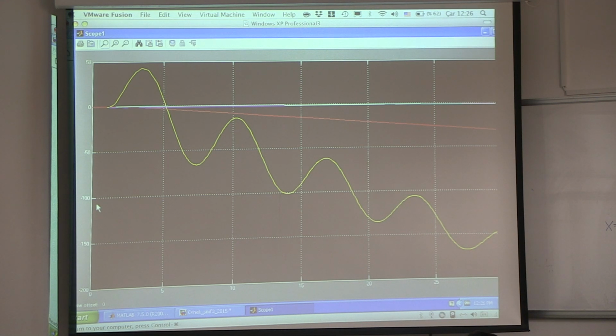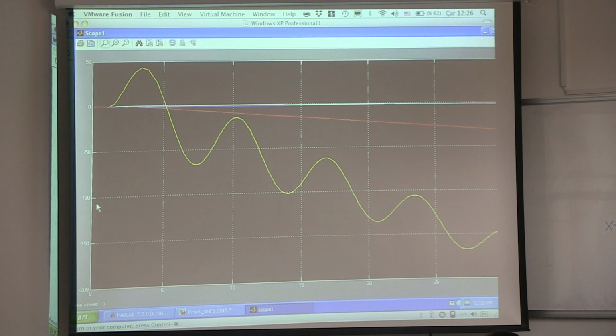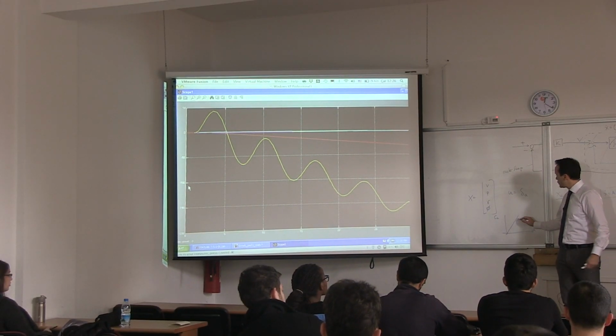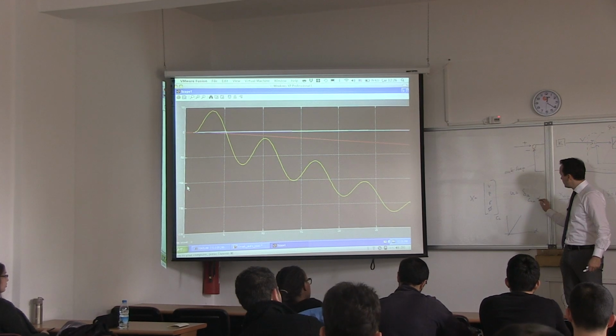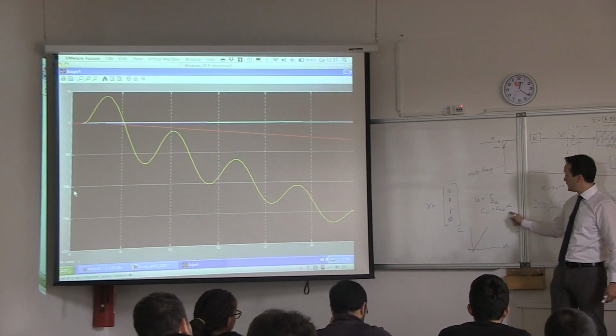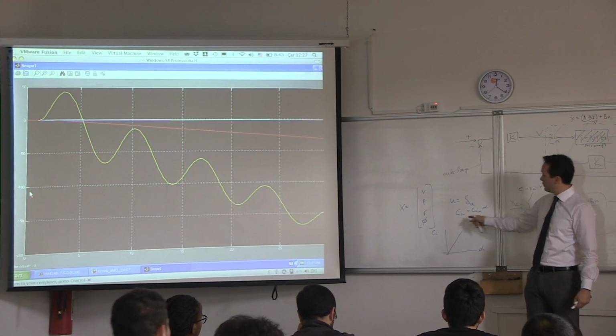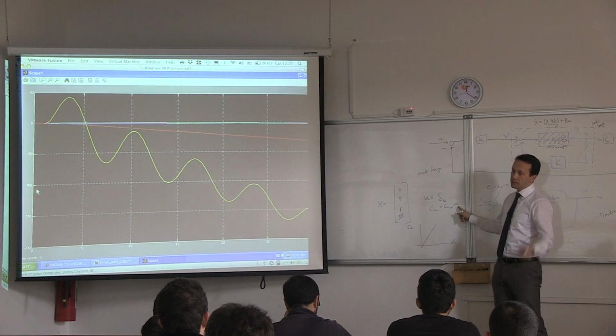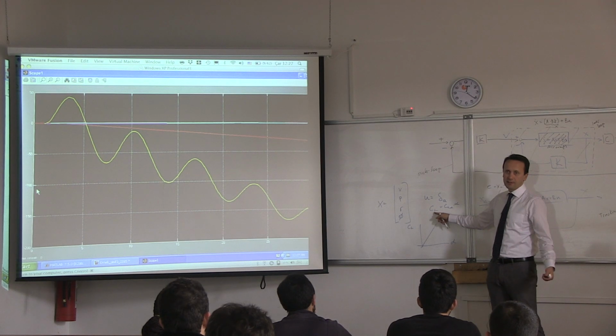It goes to infinity. I tried to explain it to you at some point. I mean, remember the CL alpha graph, for example. If you just use a linear model over here, you can just use CL alpha times alpha, and that is equal to CL, right? This is what we use sometimes to calculate CL. What if alpha is 1000? You get a very large CL. Is it realistic? Of course not.